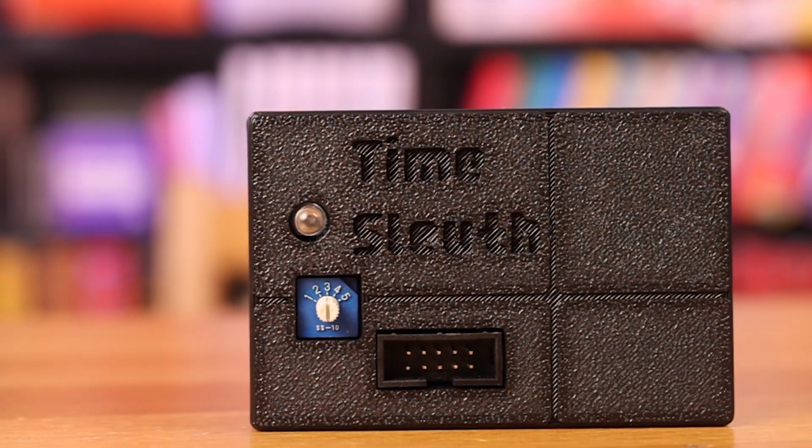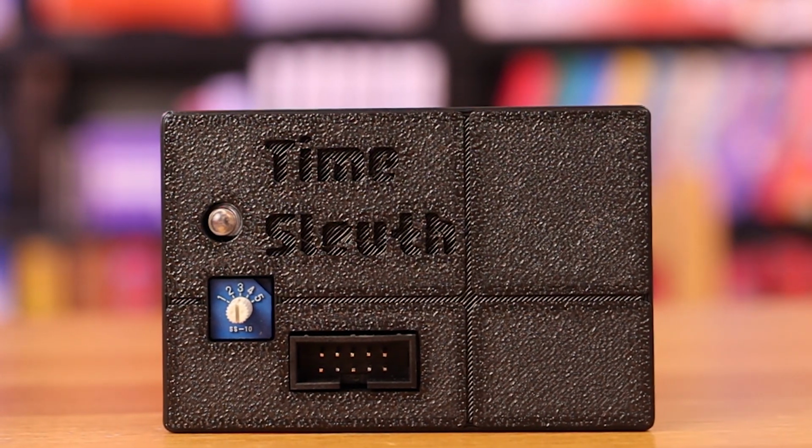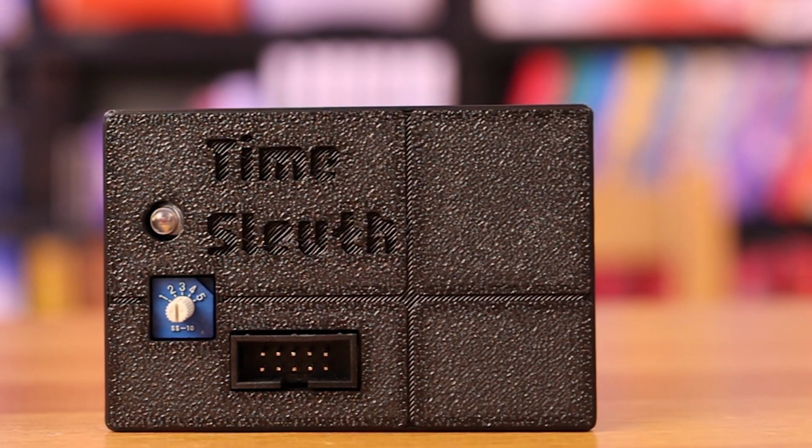If you're a speedrunner and sometimes you're making that frame perfect jump and other times you're not, maybe it's like what I was showing with the VGA to SCART adapter. There may be some device in your chain or possibly your display itself that is adding just that little bit of latency that's variable over time, making your input latency just a little bit different each time you press the button. With a device like this, you can start to measure all those little variables within your chain to get you down to as little latency as possible.